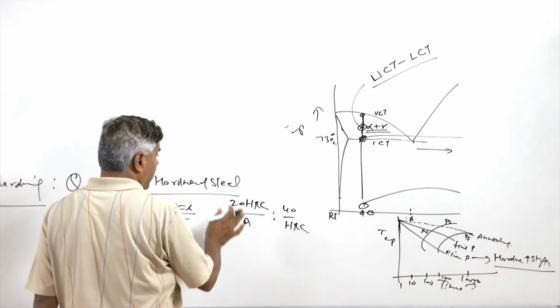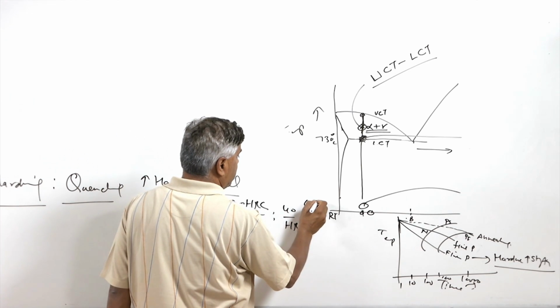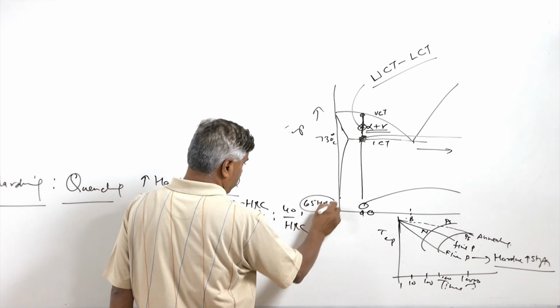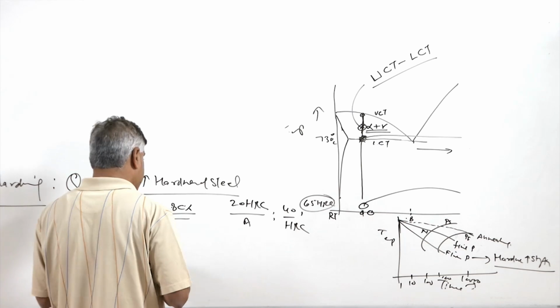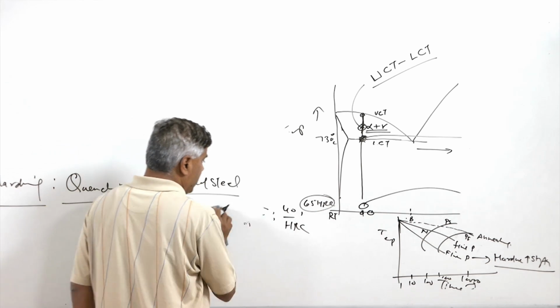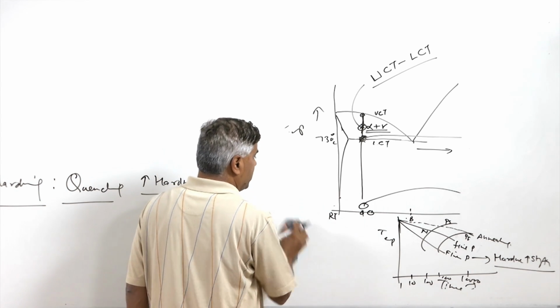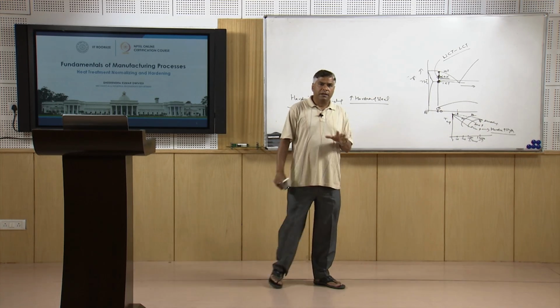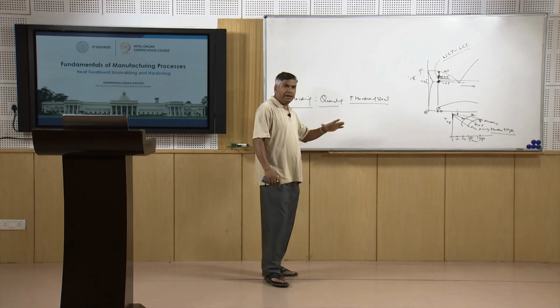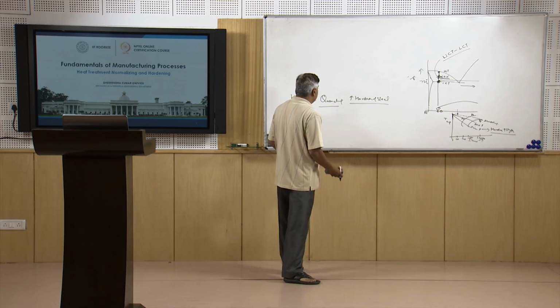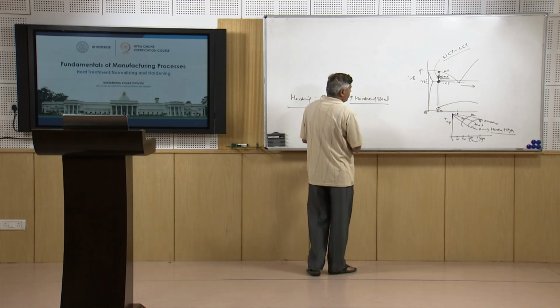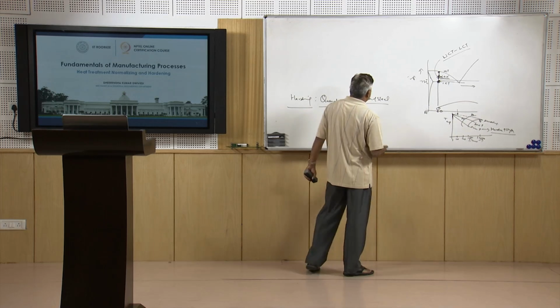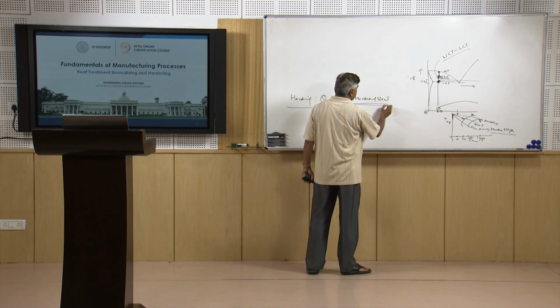But after the hardening we may get as high as 65 HRC. So a significant increase in the hardness is realized when hardening is carried out for the same composition of the steel. So steel offers such kind of capabilities wherein the properties can be altered over a wider range by changing the structure.